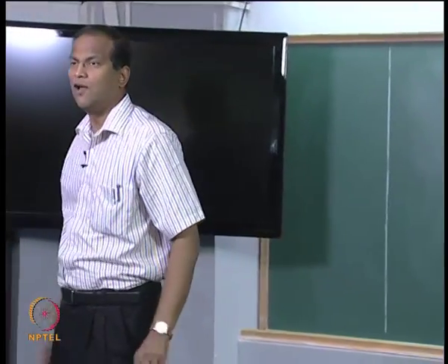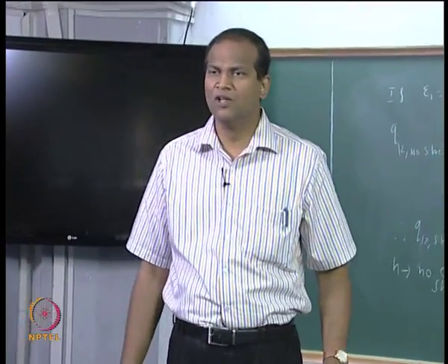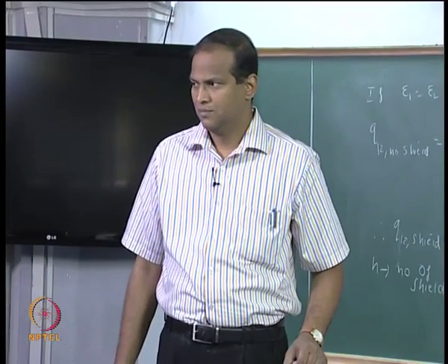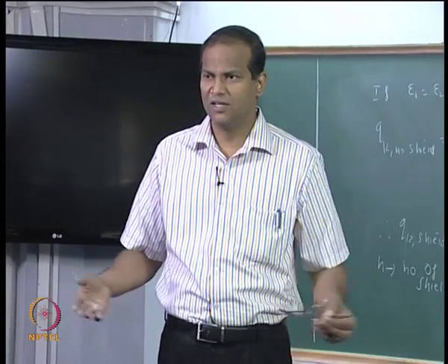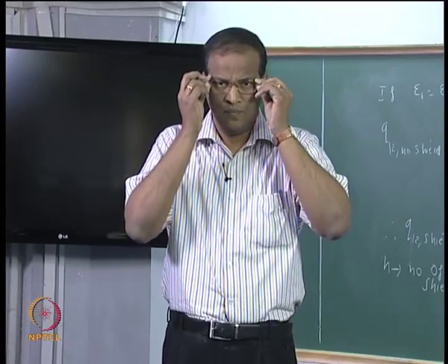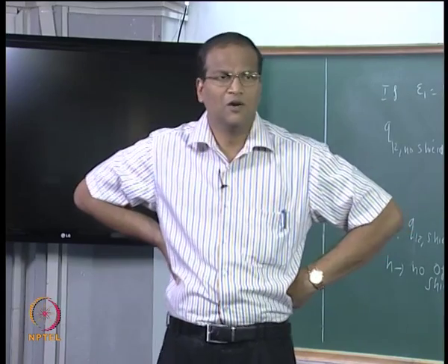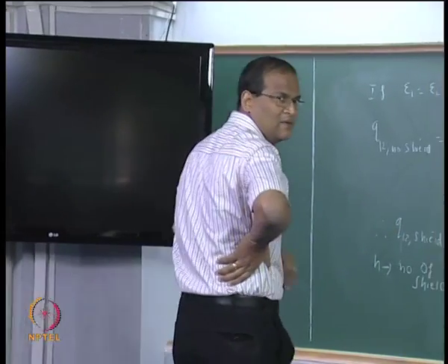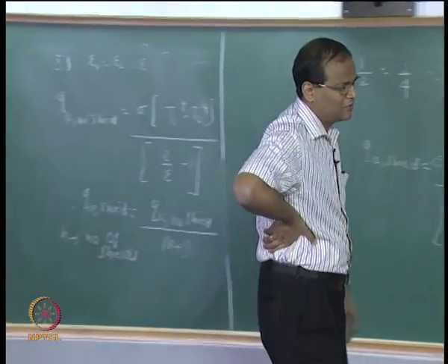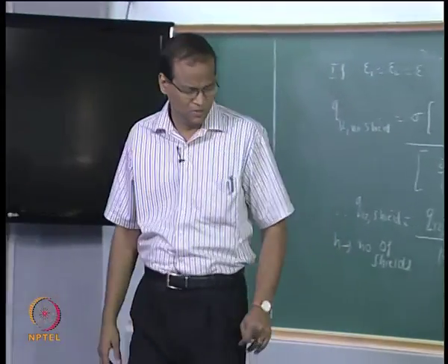So, just because you have vacuum, it does not mean that you have already insulated. If you have vacuum, you have removed the convection, and there is no conduction because there is no medium, but radiation will be there. If you have evacuated and you also have n shields, you get what is called a radiation super insulation. This is the concept of a super insulation.